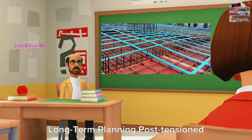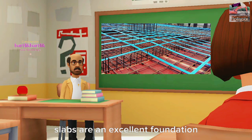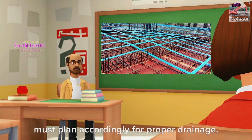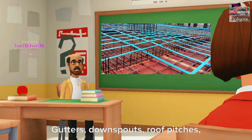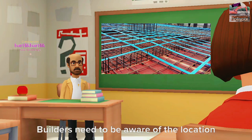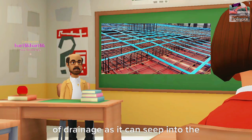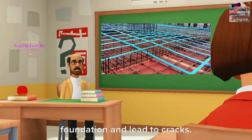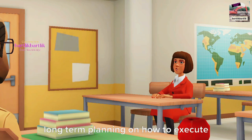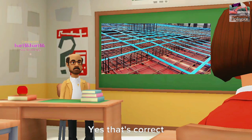Long-term planning: post-tension slabs are an excellent foundation for a new structure, but builders must plan accordingly for proper drainage. Gutters, downspouts, roof pitches, and balconies redirect rainfall. Builders need to be aware of the location of drainage as water can seep into the foundation and lead to cracks. Therefore, post-tension slab needs long-term planning on how to execute it. Yes, that's correct.